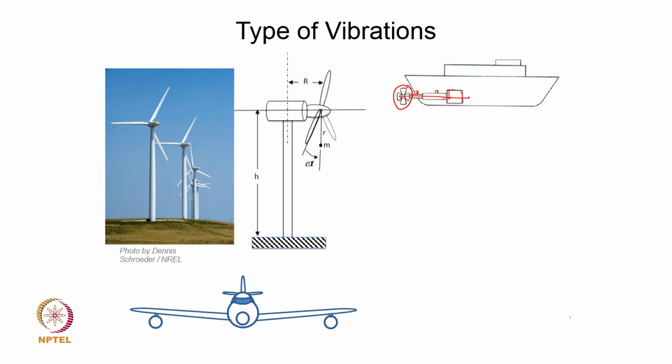In this case, vibrations along the longitudinal direction are quite possible, and of course, that does not stop it from vibrating laterally as well. So, you will need to analyze and investigate the longitudinal vibration of this propeller shaft. Once estimated, the natural frequencies need to be kept away from the excitation frequency. So, the rotational frequency and its link with the natural frequency of vibration needs to be established to ensure that resonances are not set up anywhere. Otherwise, you all know what the consequences of resonance are.